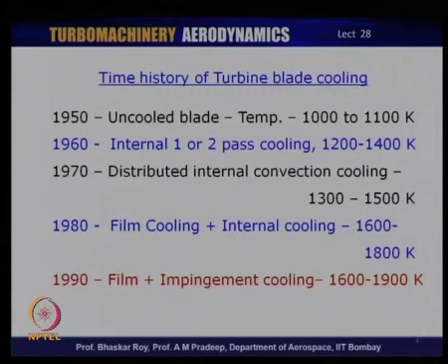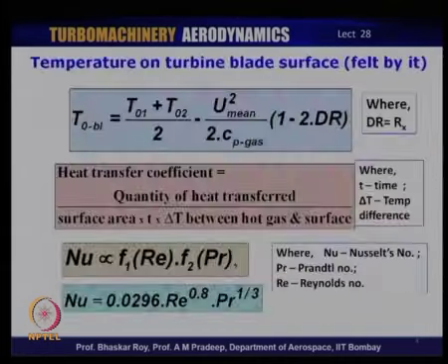It involved microchannel cooling methodology, the science of which is well known, but the technology is not quite available as of today. And the porous material that can withstand the stresses in a turbine blade has also not quite matured as of today, to the best of our knowledge. So, the turbine technology has matured hugely over a period of 50 years and has resulted in engines that are more powerful and of course, indeed smaller in size.